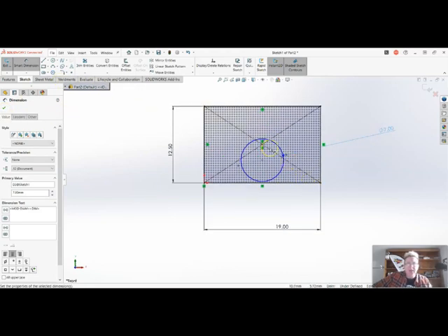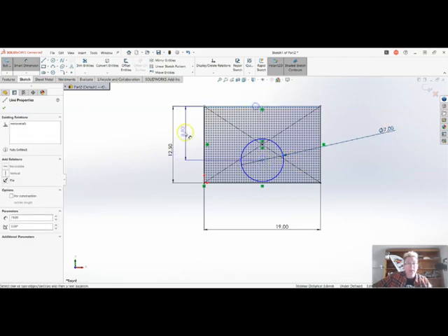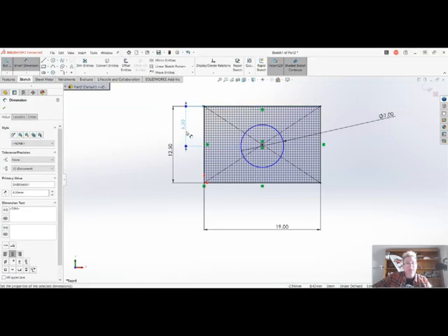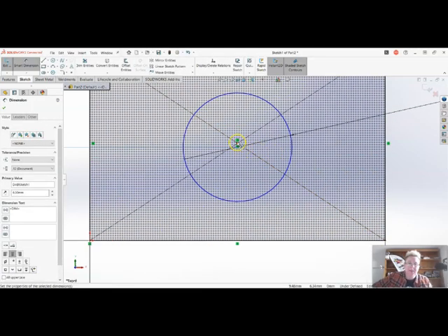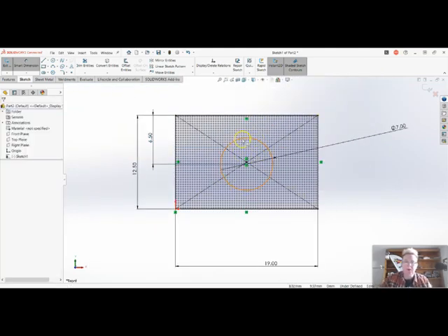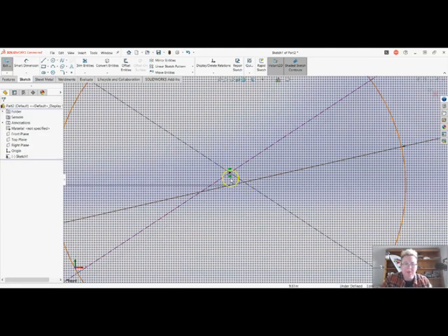What we want to do is half of 7 is 3.50. This is going down 10 millimeters. So let's take 3.50 off of 10, which is what, 6.50. So if I go there and enter 6.50, oh look, it's almost center. It's almost center. What I want to do is make sure it is going to remain center.